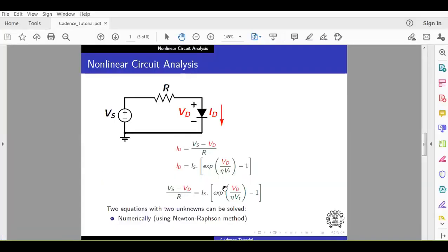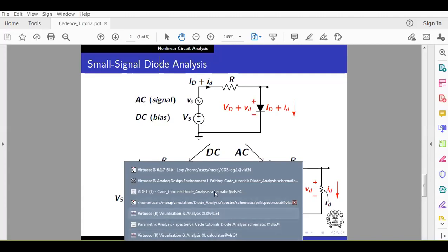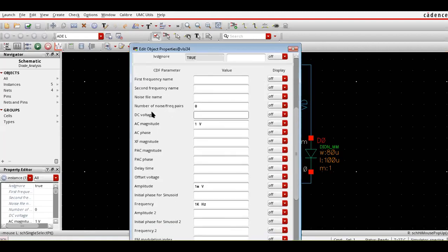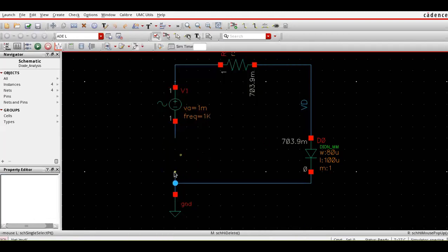So that's it. For understanding this, we took two sources, VS and this small AC and DC. Actually, we don't need this bottom source, because this VSIN has the DC voltage also. It will add a DC, it will add some AC component, and this AC magnitude is completely different. It is only used in AC analysis, and there this DC and these amplitudes are ignored. So we can keep only VS and eliminate the other. We started this way only for brief understanding. Now we can ignore it.